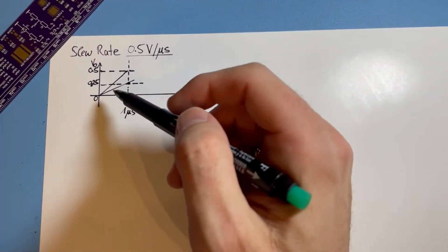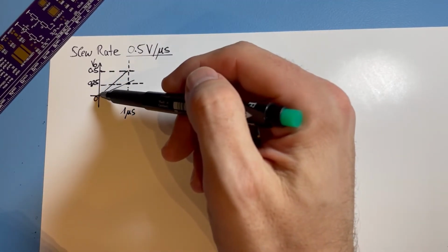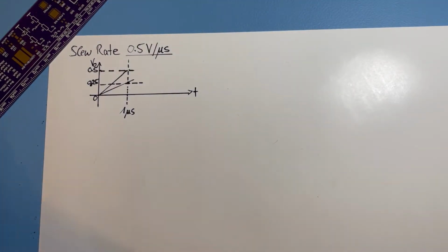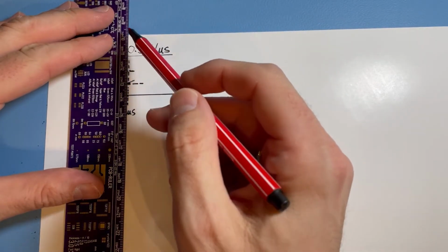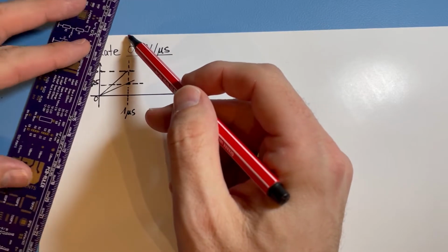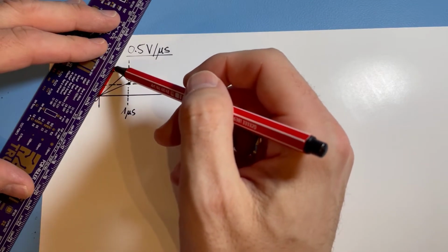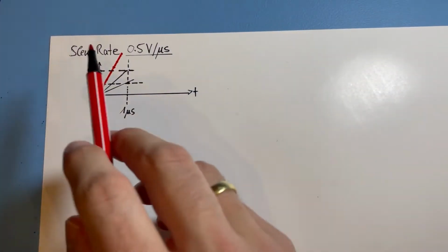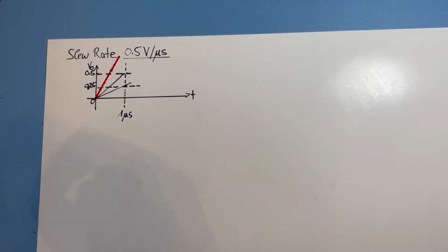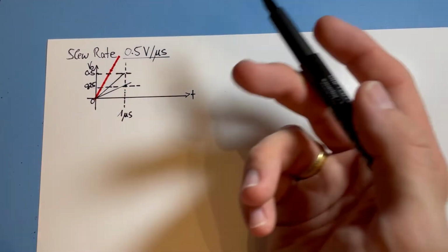But if somebody wanted the device's output to rise to 1 volt in a microsecond, that would be a much steeper line here. Perhaps we draw it in red, so we signal that this is not possible. So double, we will end up around here. Somebody wanted our device to rise to 1 volt, and we can see that would not work, because we can only rise as fast as 0.5 volts per microsecond on the output of our device.